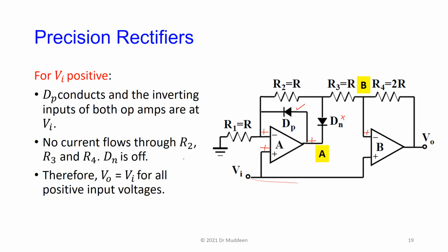And now you can see what the current flow is around here. If here is V positive, then the current coming through here is going to be Vn over R. But here's Vn. This is an inverting amplifier, so here's Vn.